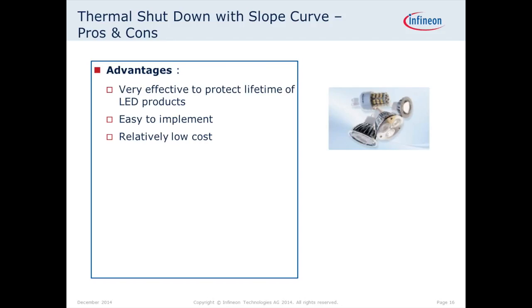So as mentioned, you can protect the lifetime not only of the IC but of the LED products. It's also very easy to implement. We are talking about classical DC-DC buck LED driver ICs, just with a few components around it. And the cost is also quite low, since you can avoid an external NTC.